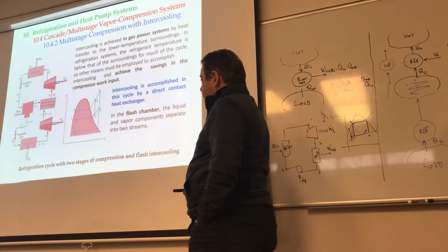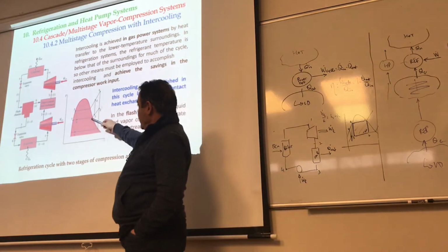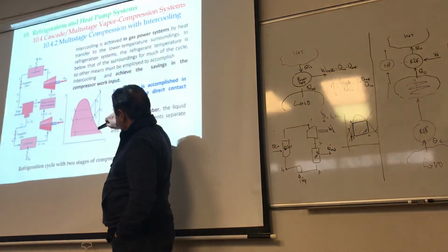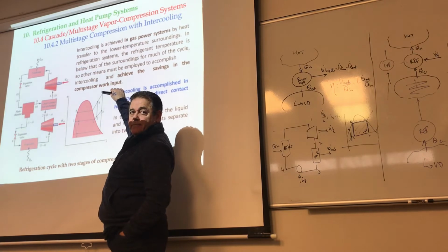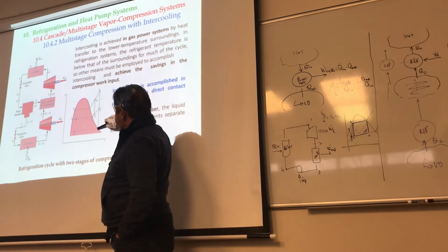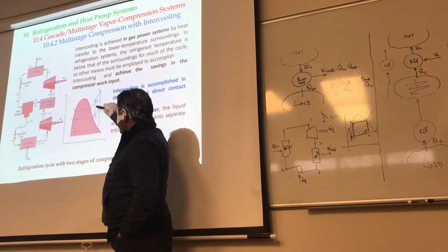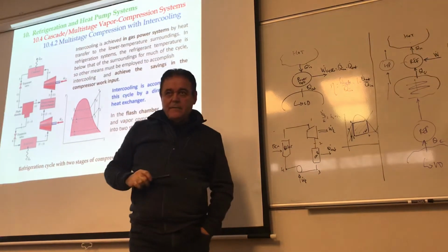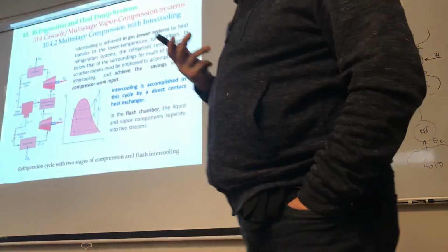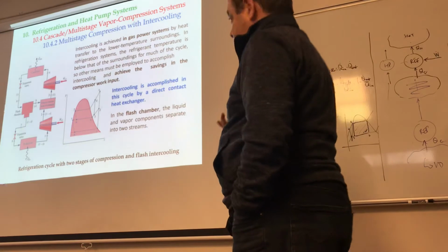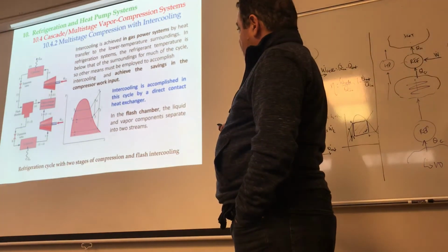So what is the whole benefit of here? If we did not have the multiple stages, we would have gone directly between 1 and A, right? By doing the multi-stage, I went to 2, and so on. What did I do? I removed this little area there, and that little area is heat, equivalent to some amount of work, right?